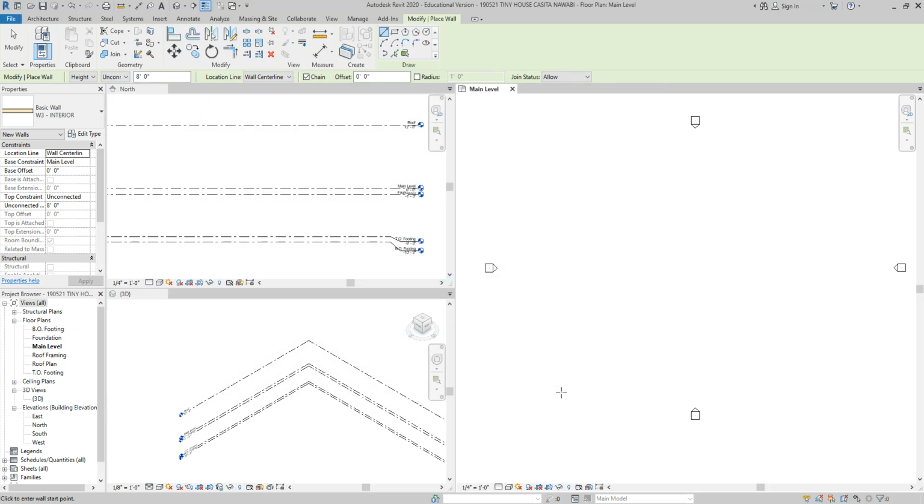So now we've gotten 2 out of our 3 wall types done. For our third wall type, what we could probably do is just duplicate W3 and make it a 2x6, right? Does that sound right to you guys? Because looking here on our list, interior wall, about 2x6. We don't know if it's a structural wall or a wet wall, but it's definitely a thicker wall.